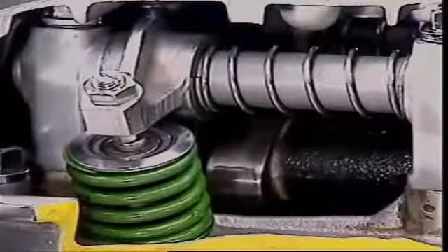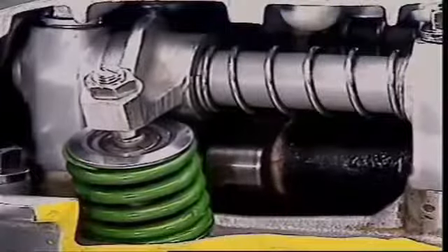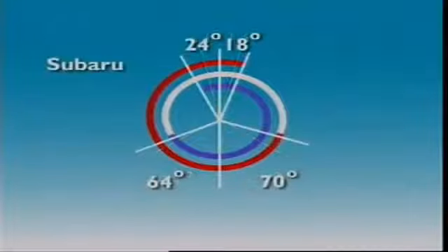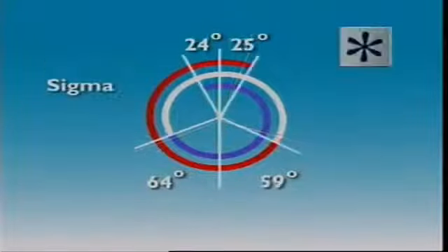The cam lobe performs three jobs. It opens a valve at the proper time and gives it proper lift. It lets it stay open for a sufficient time. Then it lets it close at the proper time. Accurate valve timing is crucial. Valve timing can vary from engine to engine, as set out in manufacturer's specifications in the valve timing diagram.